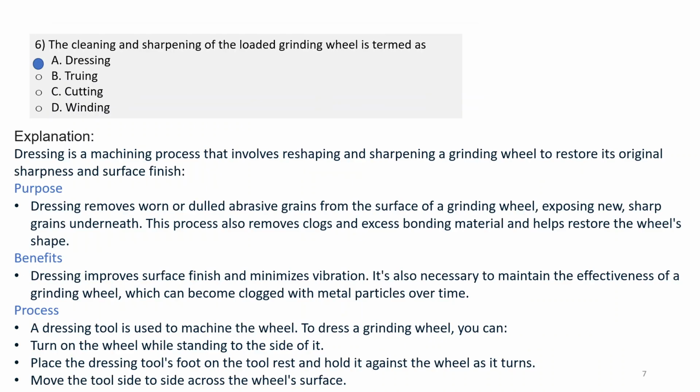Sixth question was: the planing and sharpening of the loaded grinding wheel is termed as? Your answer will be dressing. Dressing can be defined as the machining process which involves reshaping and sharpening a grinding wheel to restore its original sharpness and surface finish.